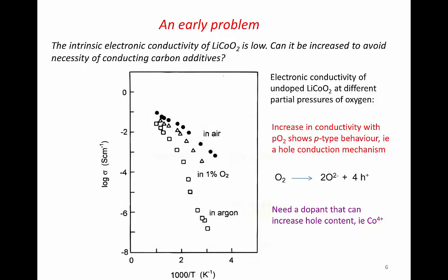So just to orient you with this graph, a value of 3.3 in 1000/T is about room temperature. So room temperature, 1000/T, 3.3 on the horizontal scale at the bottom. And then the conductivity values are shown here between 0 and -8. So 0 would correspond to a resistance of 1 ohm. And so this is the high conductivity. So for high conductivity at low temperatures, we're trying to get our materials up towards the top right corner of this diagram.